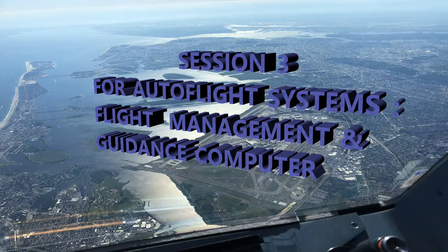Okay, so flight management and guidance computer. Just kind of reiterate here, just remembering management and guidance, right? So these are the 2 parts to the FMGC. Guidance has to do with flight plan and the control of the aircraft, using the navs. So guidance, we're talking about the navigation and the use of the inertial reference system, so your IRS, alignment through the MICDUs, okay, and then all your navigations, which you probably haven't covered yet, but navigation, with all your different devices there on the craft.